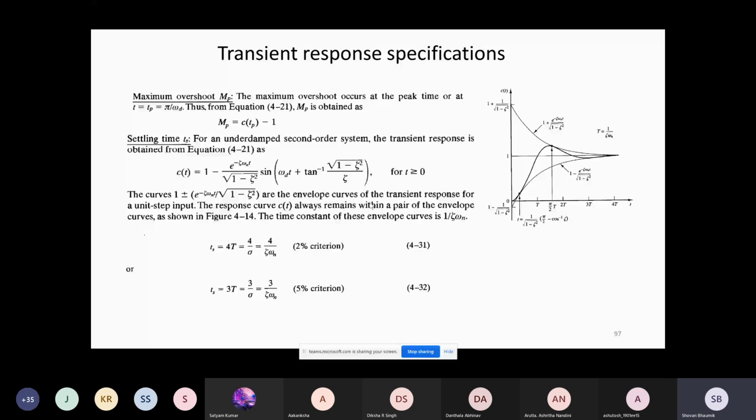Many times, whenever you have a measurement system, you know the system, you can design it, you can model it with the help of physics. Sometimes it becomes very complicated and you don't know what is inside. That is very difficult to model with the help of physical laws. Then you can use a data driven approach. You can give many inputs, see the outputs, and from there you can determine the transfer function, how, will come very soon. And from there you can calculate all the time parameters.